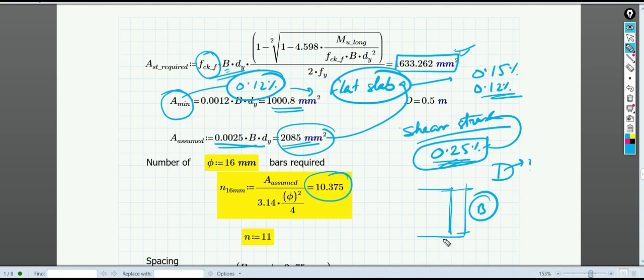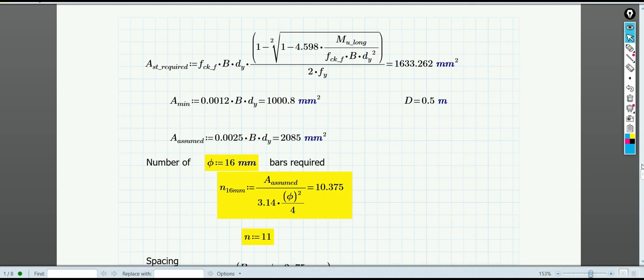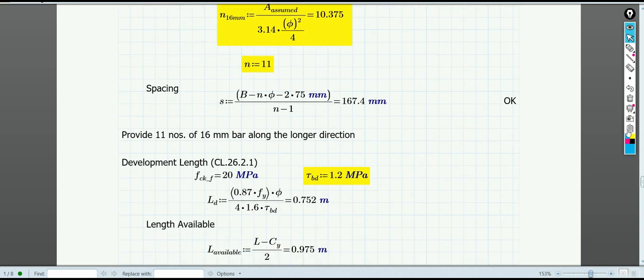And yeah, the next thing is that as we are now only calculating the reinforcement for the longer side, always remember that in the case of the beam also we discussed that while providing the reinforcement at the beam column joint, you have to provide some development length, right? So here also, because of the upward reaction of the soil, the whole footing might deflect something like this, right? With this, whatever reinforcement you have will be under tension, right?